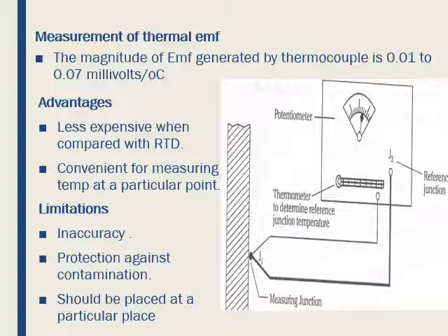For the measurement of thermal EMF, the magnitude of EMF generated by the thermocouple is 0.01 to 0.07 millivolts per degree Celsius, which is good enough. The other advantages are that they are less expensive when compared to RTD, and convenient for measuring the temperature at a particular point.